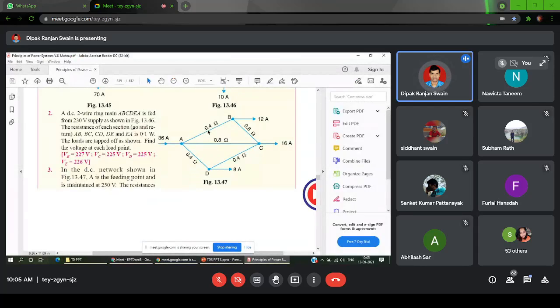You have calculated the value of current. Okay. So the current in the section AB will be 17.6. Current in the section BC will be 17.6 minus 12. Okay. So we need to find the Thevenin voltage; we remove the load, so we are finding the open circuit voltage. Here the open circuit voltage is the voltage between the point A and C. Okay. So that voltage is equal to the drop in the section AB and the drop in the section BC. So calculate current into resistance in both the sections, and that will be equal to VAC or V Thevenin.